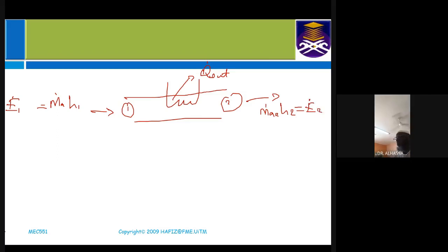And the energy of the air that is flowing out is given by this, E2. So from energy balance, we have total energy in should be equal to total energy at the outlet. So we have here E1 is going in, and Q, watch out carefully, Q out is leaving. So we are taking some heat out of the system. So we have Q out plus E2, this is also leaving the system.